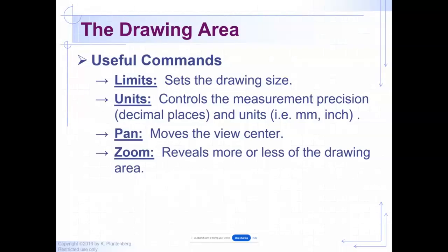Okay, so here are some things we're going to talk about. Limits and units. When you set up a drawing or you start a project, the first thing you need to do is tell AutoCAD how big of an area you need to use so that zoom will work correctly. Otherwise, it may not even let you draw outside the limits.